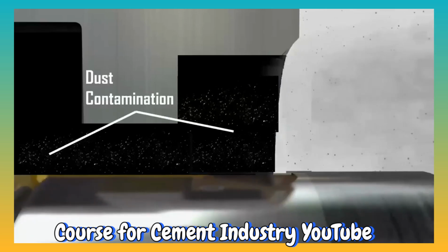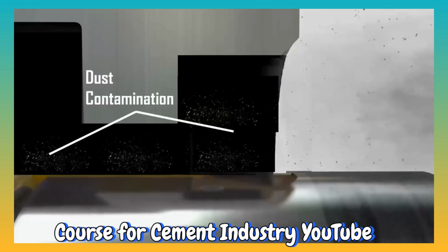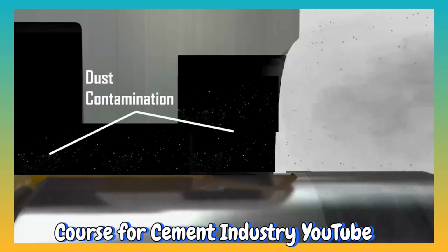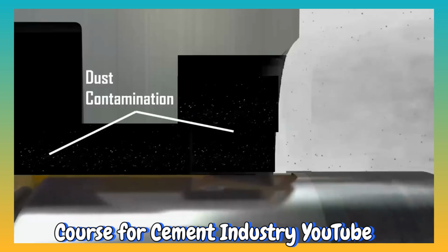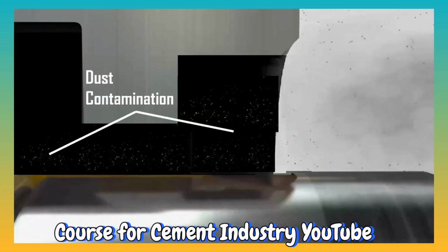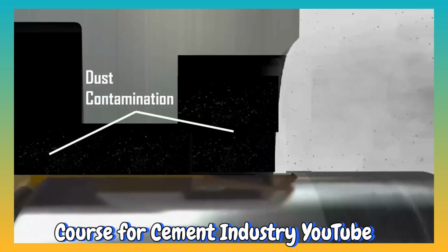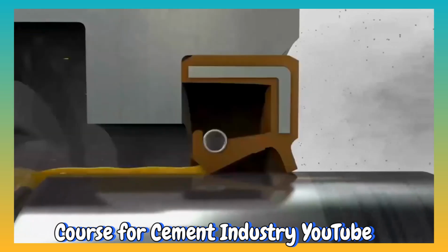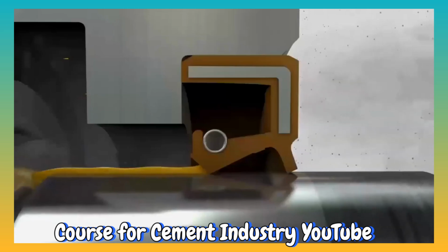Conditions such as rain or the shaft protruding underwater allow water to enter. Dusty conditions also allow dust particles to enter the engine compartment. The oil seal closes the inlet so that no contaminant from outside can enter. Simply put, the oil seal protects the engine by closing the gap between the shaft and the engine housing and separating the conditions inside the engine from conditions outside the engine.